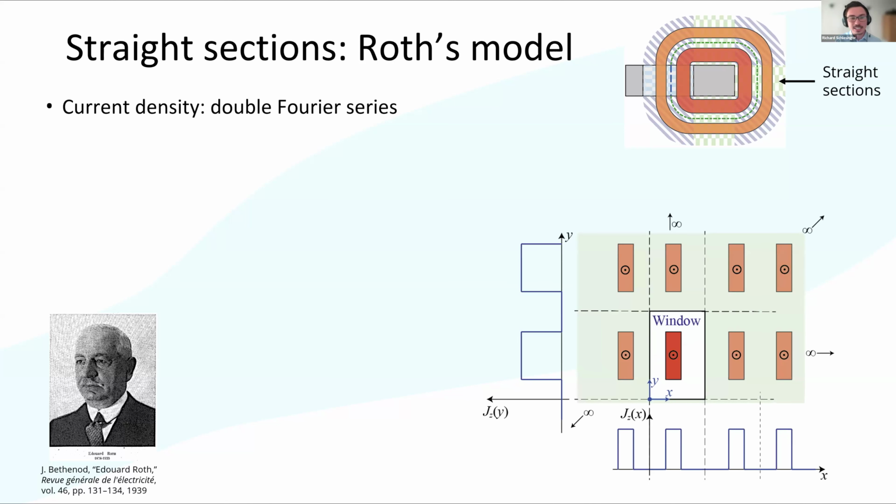Okay, but how does he actually derive the magnetic energy per unit length, and from that the leakage inductance per unit length? He starts by assuming rectangular currents and uses the method of magnetic images to get the correct boundary values for the magnetic field.